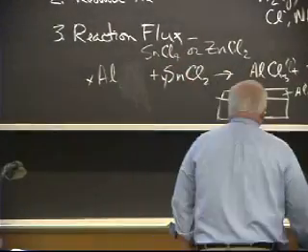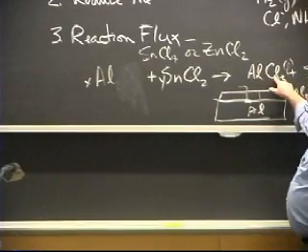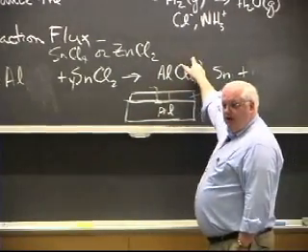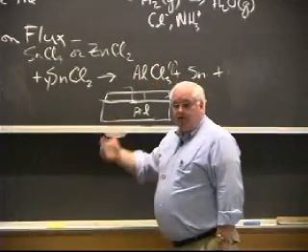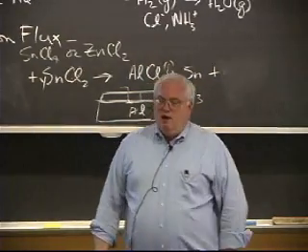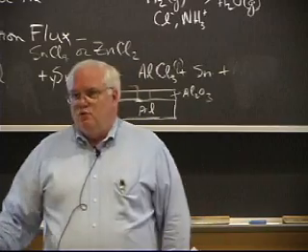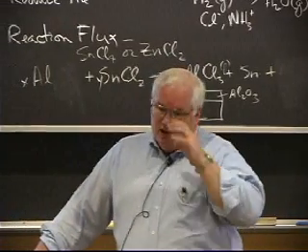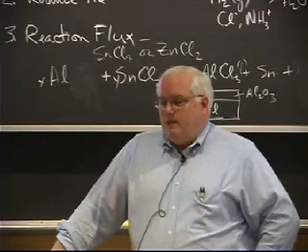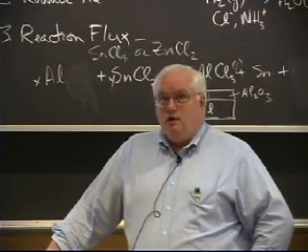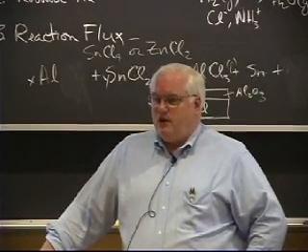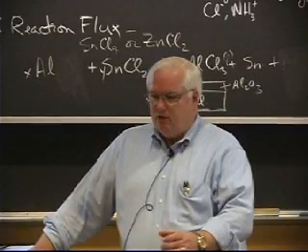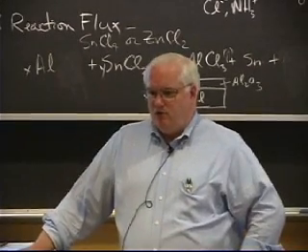And what happens if I form aluminum chloride in the presence of moisture, I get aluminum oxide and hydrochloric acid. Okay, and that doesn't do much of anything. And so a little bit of moisture will screw up these fluxes. You can buy these fluxes commercially, and in New England, where we have lots of nice humidity, you can open it up.